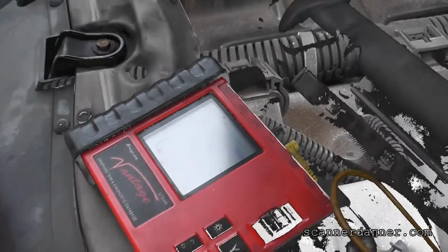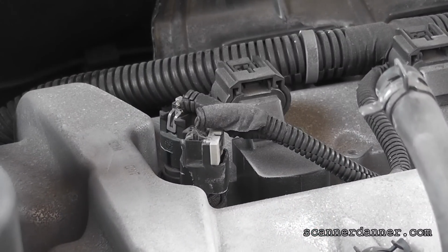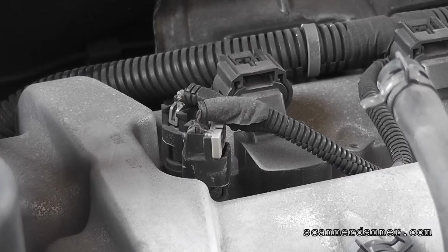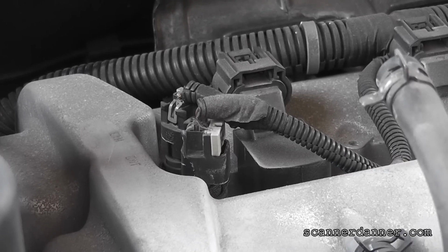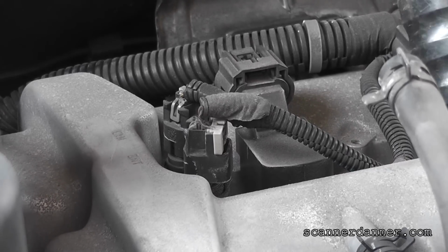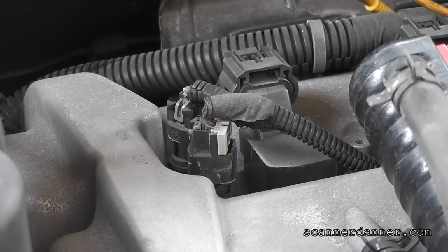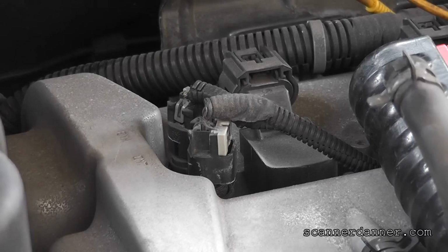So now to check this solenoid. We've done our homework already. We know that it is power side switched. We know it is a pulse width modulated signal. So for our first measurements here, we don't expect with the key on to see any voltage on either wire. Before I do this measurement, let me just talk about this for a second.